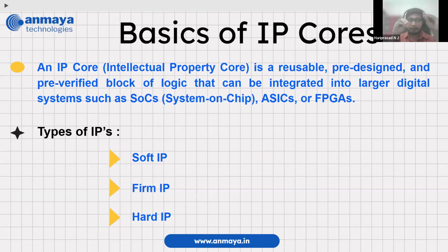It is going to use the FPGA resources and build the functionality. Let's say you designed one FFT IP. When you synthesize it on Vivado, it is going to choose the lookup tables, registers, DSP slices, and it can place them anywhere in the FPGA.